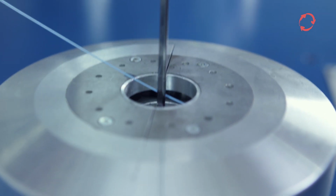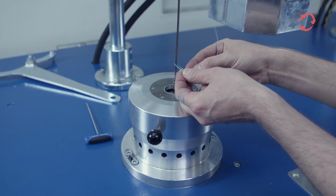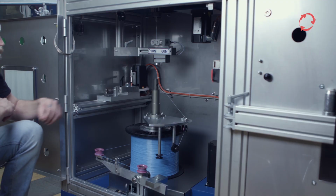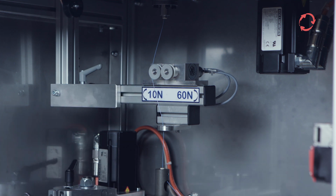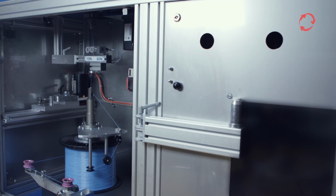Tie the thread to the spiral mandrel. Make sure you pay attention to the desired winding direction. After wrapping, rotate the coil so that the thread is under tension, and then place the thread onto the appropriate thread tension sensor. Which thread tension sensor is used depends on the dimension of the monofilament and the size of the spiral. Now check again the thread course, if everything is fine.